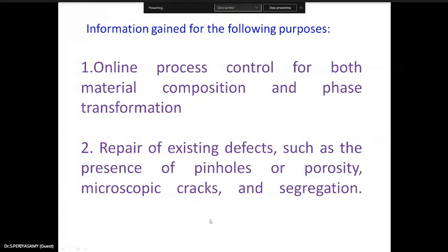So you may have porosity. The same case with entrapped gas, even a small amount of gas, even if you are using inert gases for that purpose, that may be entrapped, so you can get porosity as well as voids and holes. Then the incomplete fusion. You are depositing layer by layer.